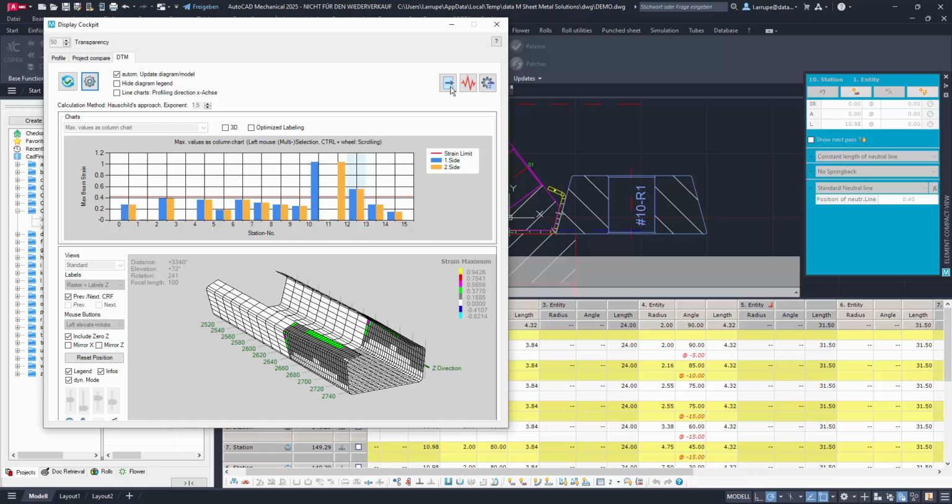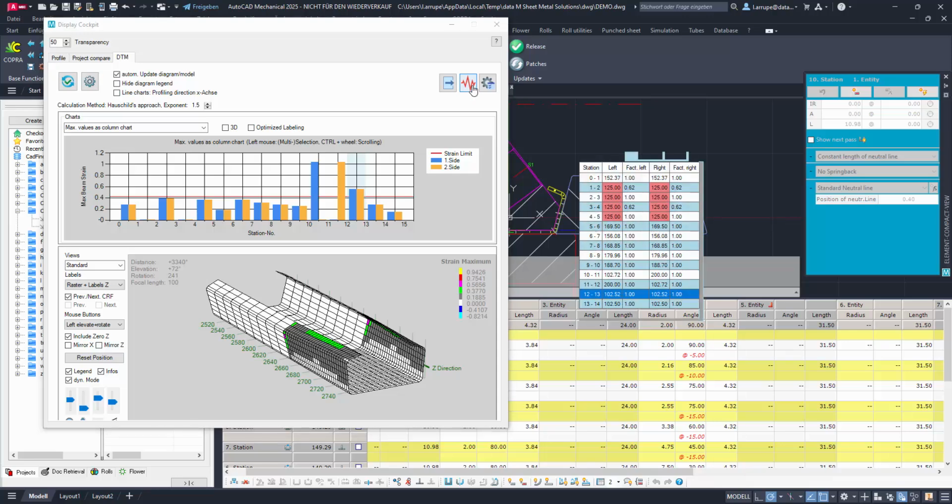We can directly have here the forming length developed explained, and we can here in the table change it if needed, if we have to change because of profile stiffness issues. We can change also the factors or the distance we get actually here.